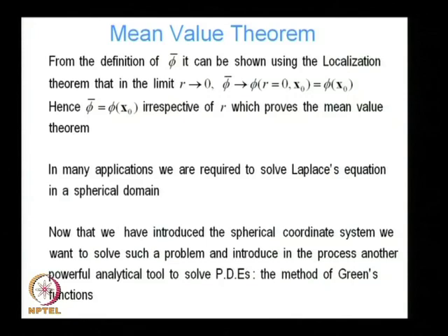and we need to solve Laplace's equation. Well, why do we need to solve Laplace's equation? Again, because in most cases we are considering irrotational inviscid flow, so potential flow. That is why we need to solve Laplace's equation.